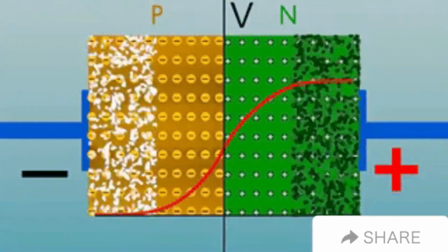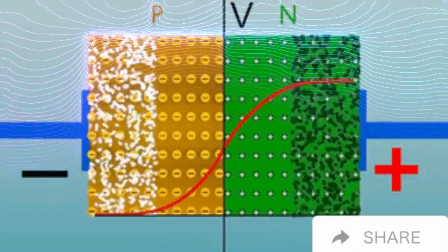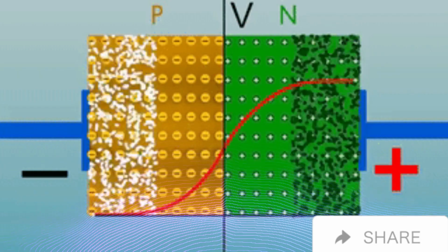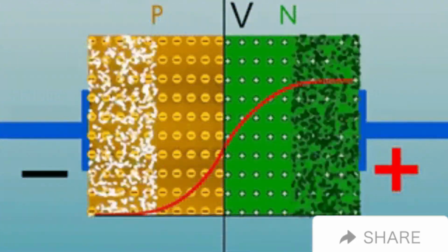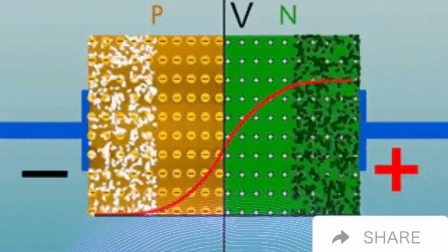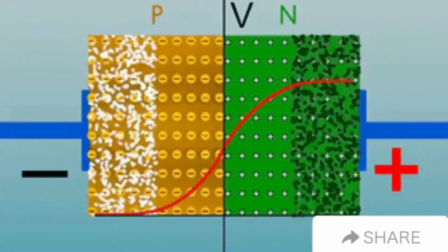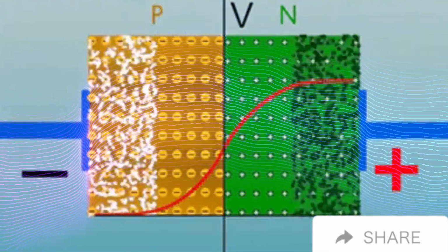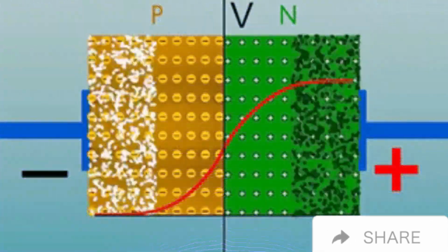Voltage drops: diodes are used to create fixed voltage drops in a circuit so that they can be used as voltage references. Other types of p-n junction diodes are used in voltage regulation, like Zener diodes. Well, that's another topic for another day.